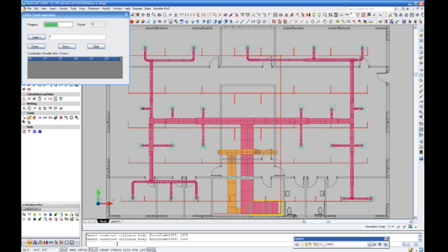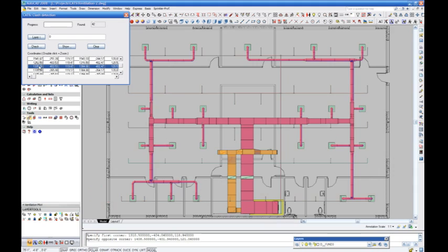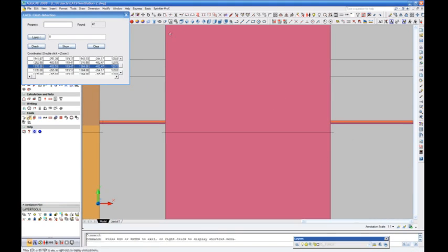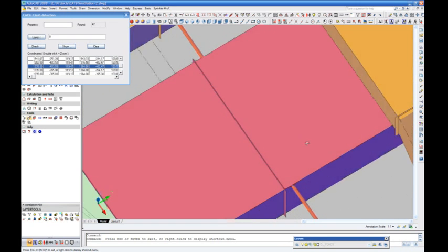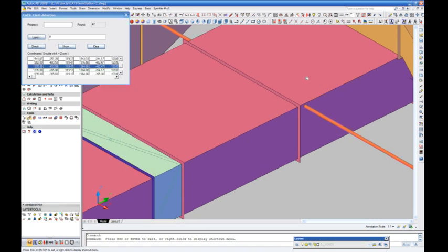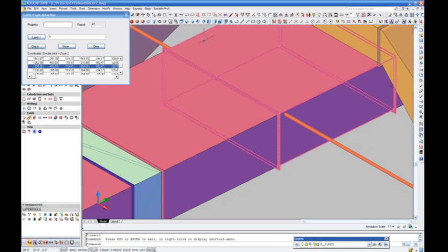The crash detection is processing each coordination point for each collision. The colliding coordinates are listed in the C.A.T.S collision detection window. By double-clicking on the collision point, you will be directed to that point on the drawing. It will zoom you to the point automatically. Here you can see that the fire sprinkler branch line and the supply duct are in conflict.